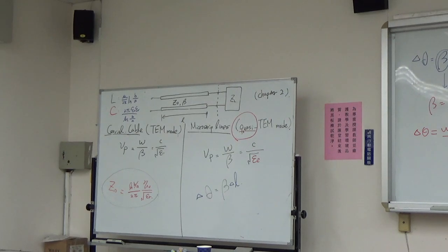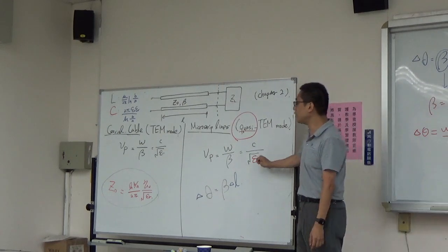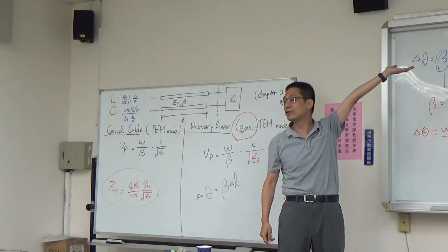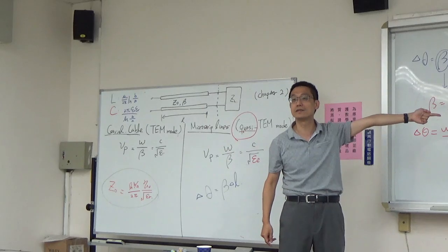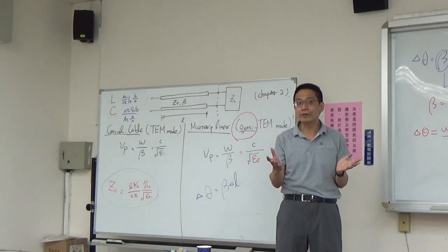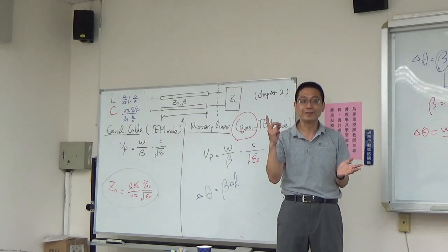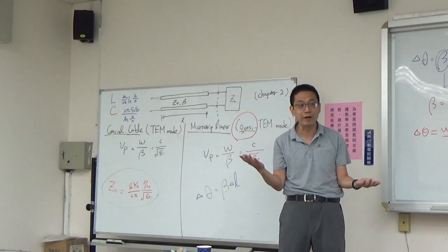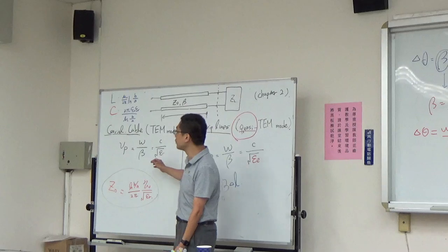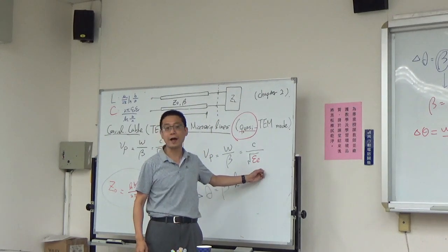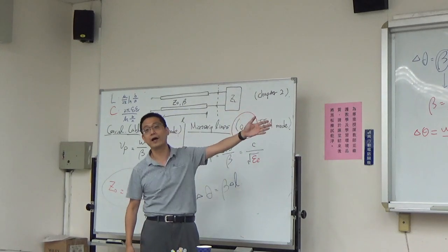If I give you epsilon R, you need to obtain your epsilon E by using the equation of epsilon E from the last page. After that, you calculate Z0. Okay? Then you can do everything we did in chapter 2. We also connect everything to each other. Remember, the question I asked you for a coaxial cable, happens again for a microstrip line, except the equations are extremely huge.